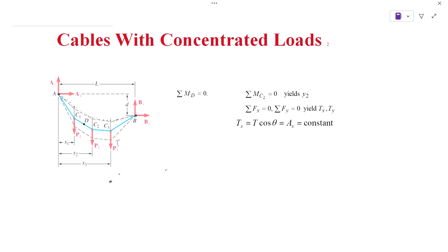So if they're like cars, this is a bridge and there are cars going through. I'm exaggerating this a little bit, but you have this movement depending on the loads, and this is allowed. This is okay. That's the design. You want things to have some flexibility and to have some movement. You don't want too much, but you don't want to have completely rigid because then you can crack. So that's why cables are so beneficial because you still have some dynamics, some displacements, but still the structure itself is going to be sound and static.